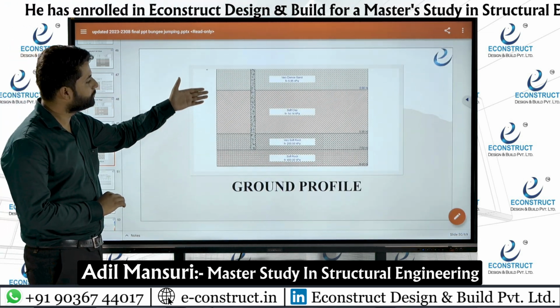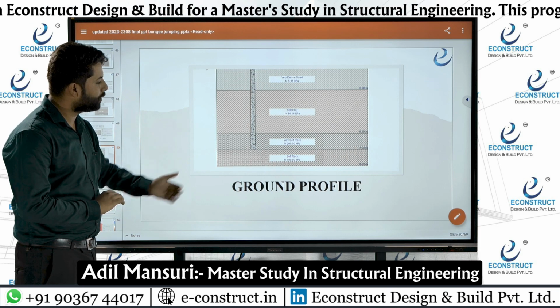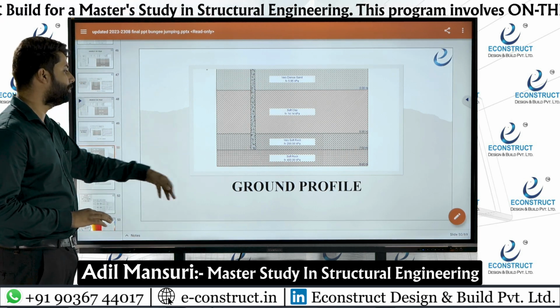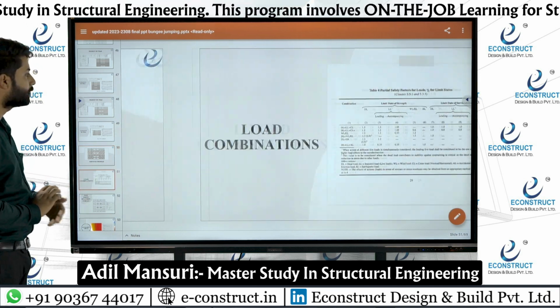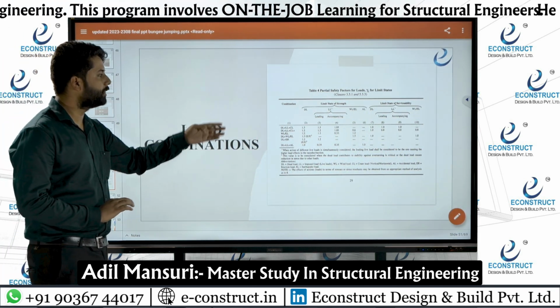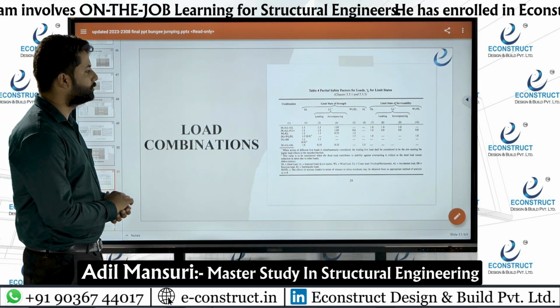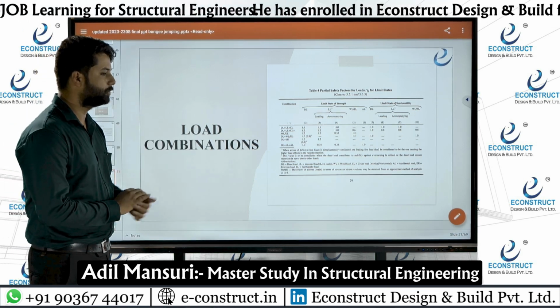As you can see, very dense and soft clay, very soft rock, and soft rock we have considered up to 15 meters like this. The load combinations for this we have considered IS 800 2007, this clause and this table, as you can see.